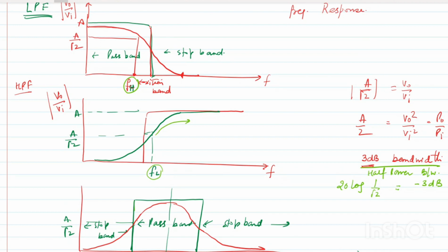If I say low pass filter, then in Scilab I'll show you the implementation and simulation. If I say that we want to design a filter of 100 hertz, that means 100 hertz is the cutoff frequency. Cutoff frequency means that there your gain will be 1 by root 2 times the maximum gain, right? So what will happen when I give the input to that filter?